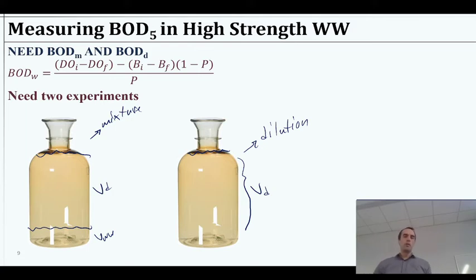So we have 2 different measurements happening, and in order to keep them straight, we have a new label here that the book provides, arbitrarily B. Okay, B is our second dissolved oxygen metric. That's for the dilution bottle. So BI is the initial DO in the dilution vial.